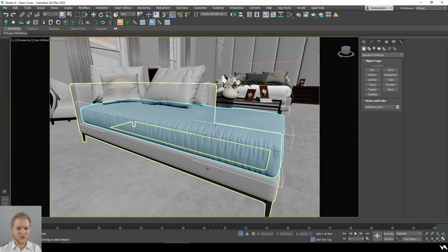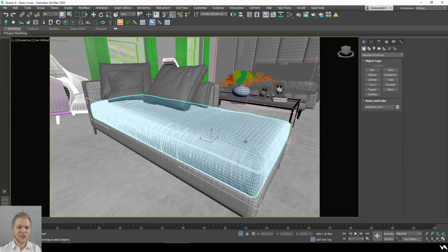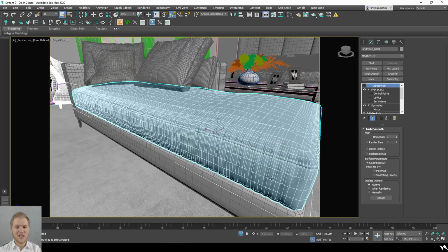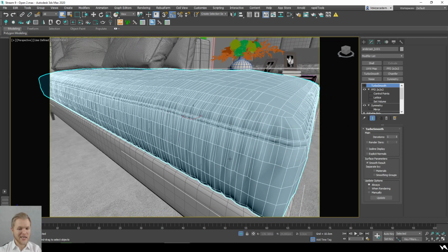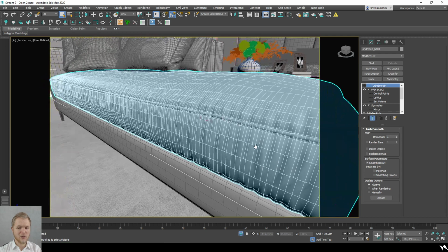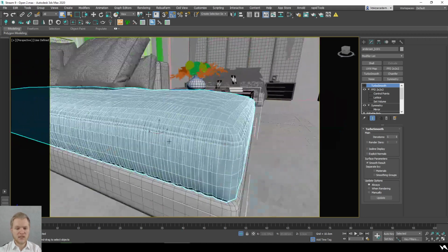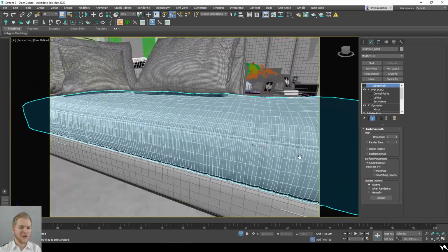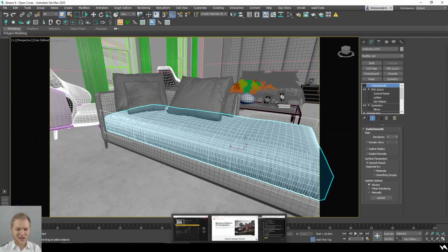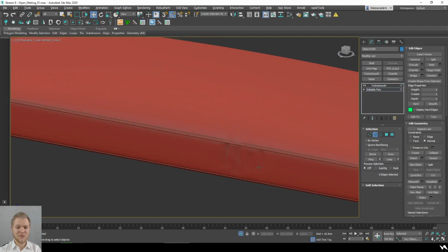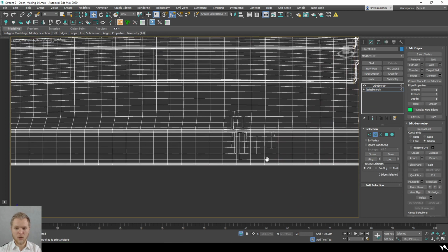And if you go a little bit further and make sure that you go all the way and create these nice wrinkles, please notice that this is just a copied element with a noise modifier, so there's a lot of trickery going on here. Before I added those chunks, I had to copy this mesh a few times. As you can see, this is looking really nice, and if you go a little bit further and add a little bit more of this chaos onto your object, you're going to get nice wrinkles. At this point you can basically see what we're going on about.